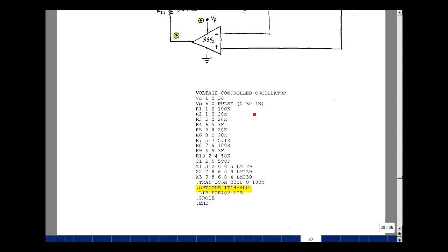Whenever we're doing an oscillator, we might want to turn on the power supply with a delay pulse. If you just apply power, Spice does a pre-initial condition check, finds all the initial conditions in the circuit, and basically it'll just sit at one point and won't oscillate. So putting a little time delay on the power supply will actually kick it into oscillation, rich in harmonics. So I delayed it just 1 nanosecond.